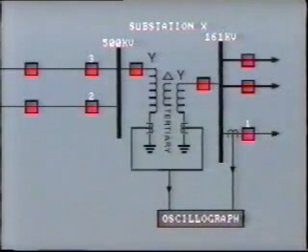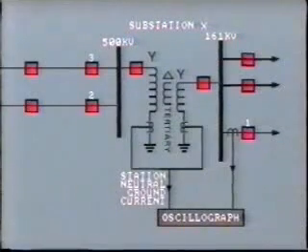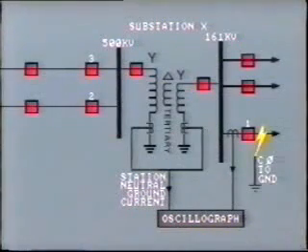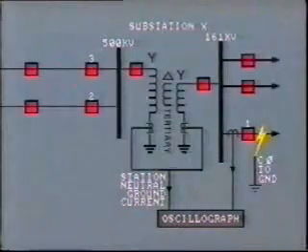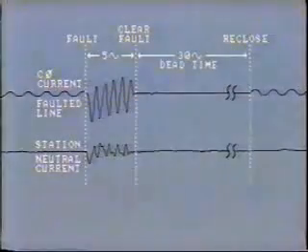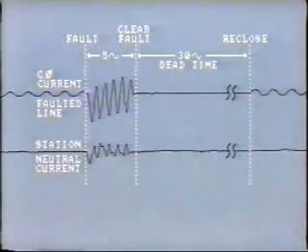The current monitored by this CT arrangement is referred to as the station neutral ground current. A single line-to-ground fault occurred on C phase of one of the 161 kV lines leaving Station X. These traces were recorded automatically by an oscillograph machine installed to capture fault information.